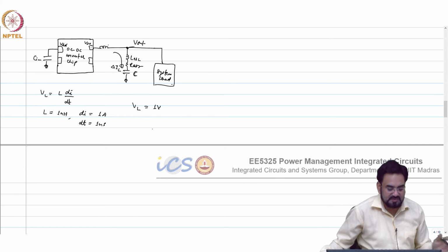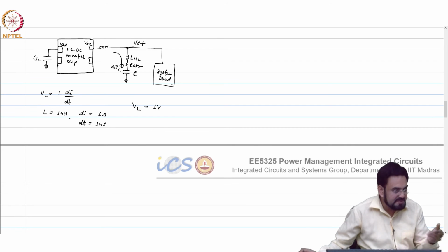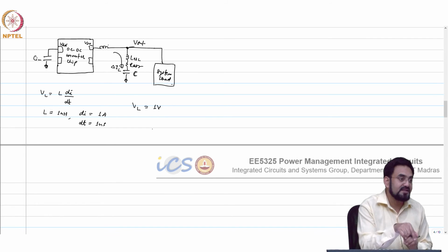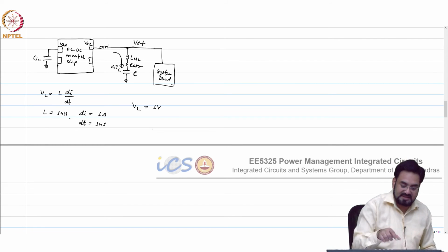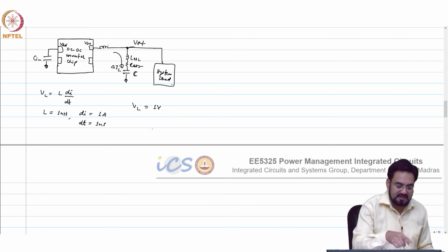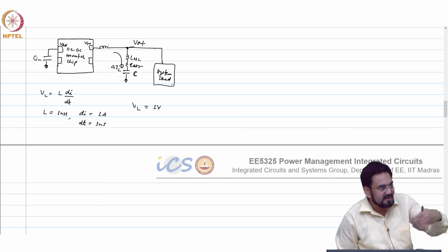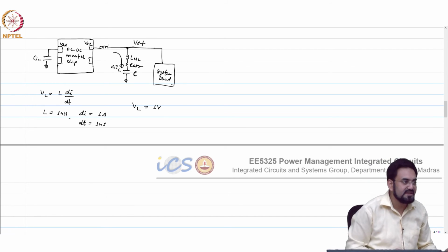If that ESL is large, let's say I can afford maybe plus or minus 100 millivolt or so, then the value of L you require here is the equivalent series inductance, or parasitic inductance, associated with that cap, which will not include the inductance of the cap itself. When I say ESL is inherent to C, but whenever you are connecting this capacitor to your VDD node or any other pin, that trace will also add, because that will be in series with ESL. So the total inductance we are looking at is maybe 100 picohenry or so in this case.